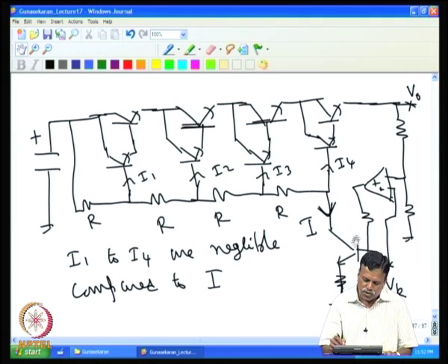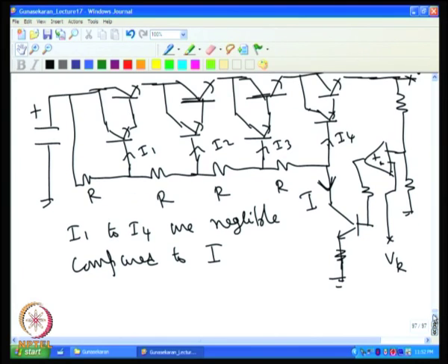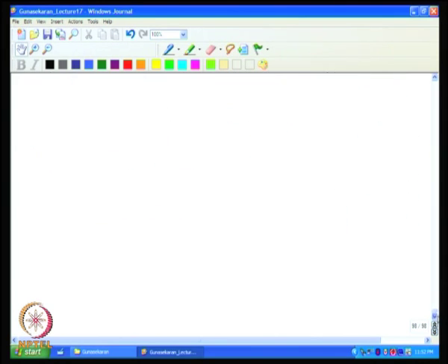Even this transistor also can be connected in series in the same manner here if required, but normally for low power you get high voltage transistors easily available. For example, BU208 gives you a 1000 volt rating, so one can use this. So, we had seen how to connect the transistor in series and parallel. So, we connect the transistors in series to boost the voltage.